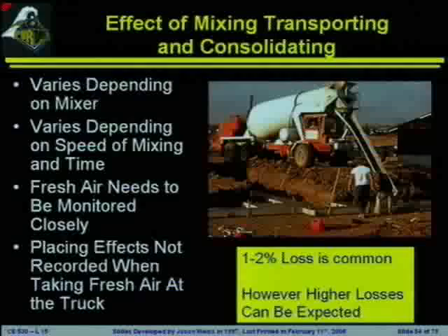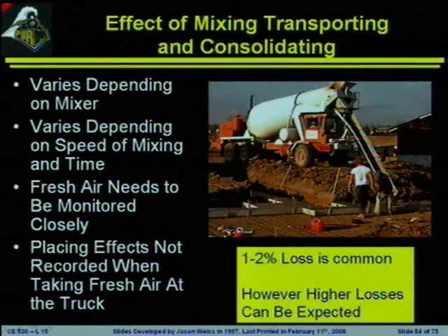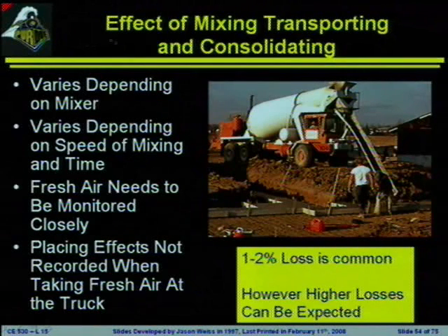So to pick up where we left off last class, we're going to talk a little bit about the effects of mixing and some of the effects of the trucks on air. Obviously, the amount of air inside the system is going to depend on the mixer and the mixing action, because what we're really doing is capturing the air and stabilizing the air while it's being created. This is going to vary depending upon the speed of the mixing